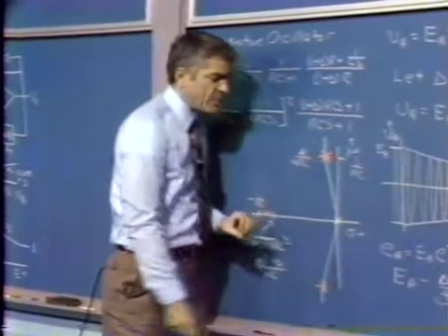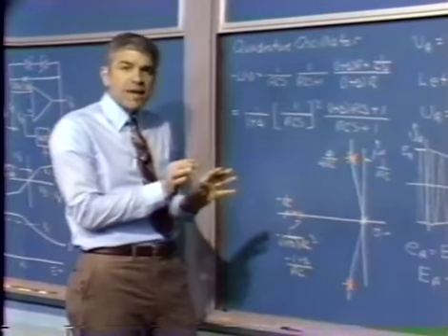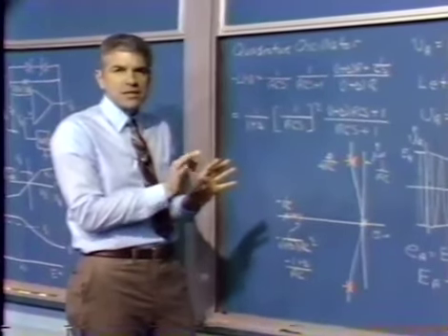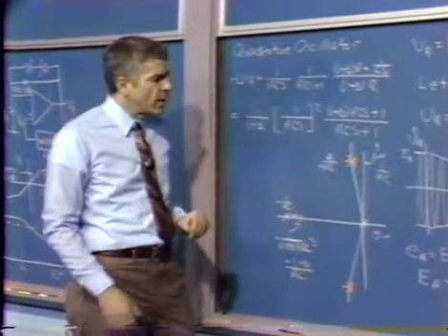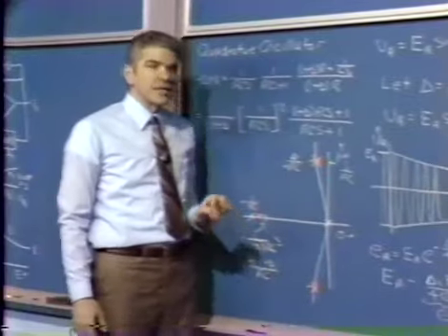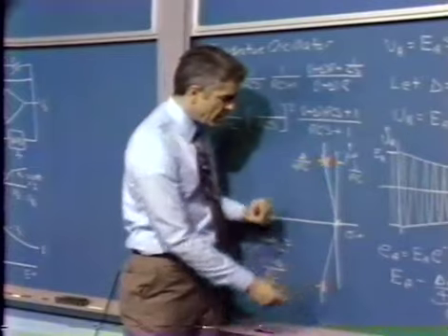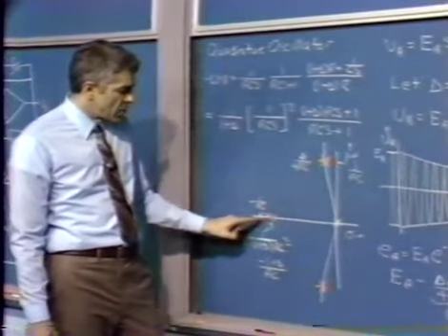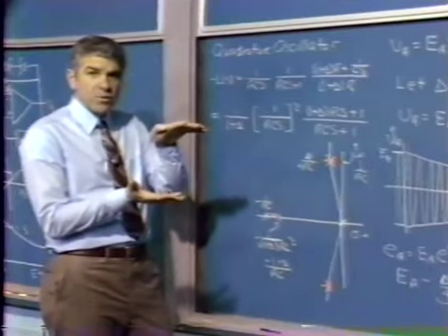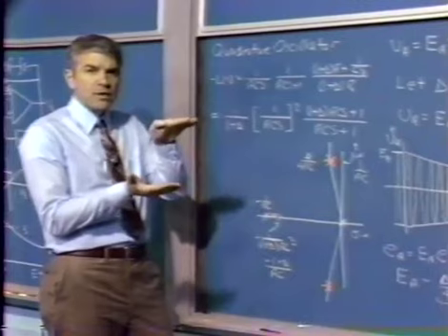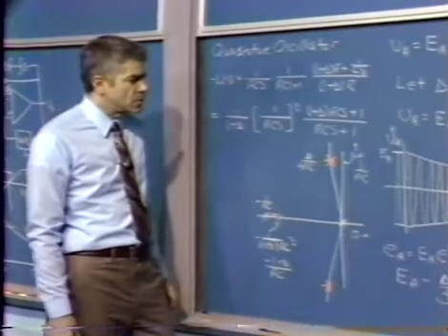lay exactly on the imaginary axis, and then from there on in keep adjusting the pot to make up for very small changes in system quantities in a consequence of temperature dependence or aging or whatever, and work to keep the output amplitude constant. To the extent that we were able to keep these closed loop poles precisely on the imaginary axis, by making this 0 lie precisely on this pole, we'd have a constant amplitude oscillation, which would be harmonically pure. We have a true linear system with a complex conjugate pair of poles on the imaginary axis.